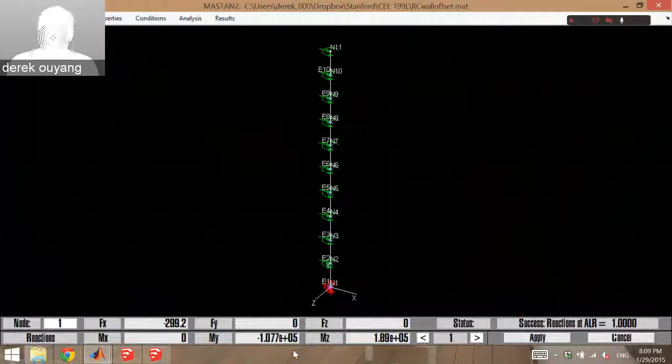this wall is going to feel a lot more work, because it's this compounded with the turning that it has to resist. Whereas this one actually has a little bit of force canceled out for it, right? It's resisting the overturning of the straight force, but the turning of the entire shear wall is actually helping it out a little bit, right? So then what's going to be the most important thing you design here? It's going to be this flange, right? Because it has the double impact.